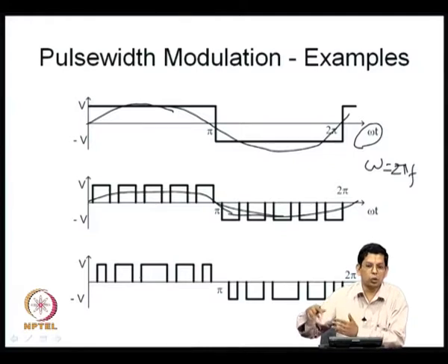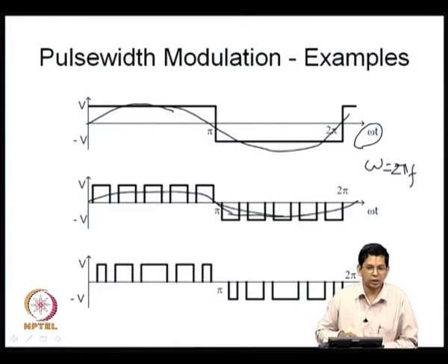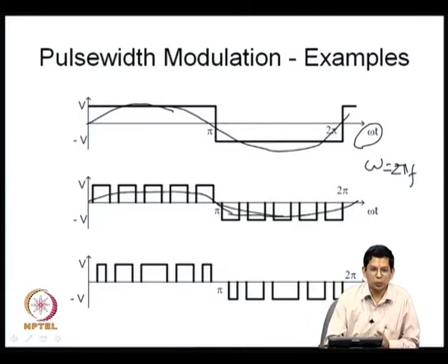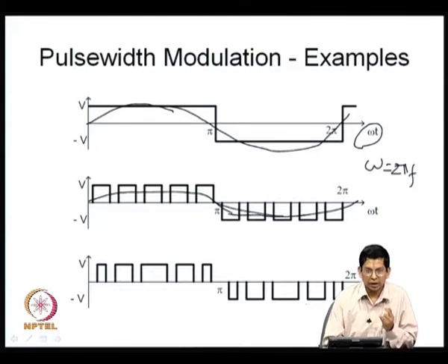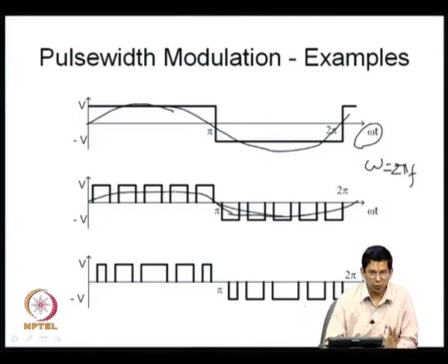You remember that the load might be inductive, typically it is inductive, and it may have stored energy. So, you need to provide a closed path, and you short that. So, you need a network of switches which can connect the load directly to the DC voltage, reverse connect to the DC voltage, and simply short the load. This is to let you get a feel for what is necessary. How this network is going to look is something we will see in the next lecture.